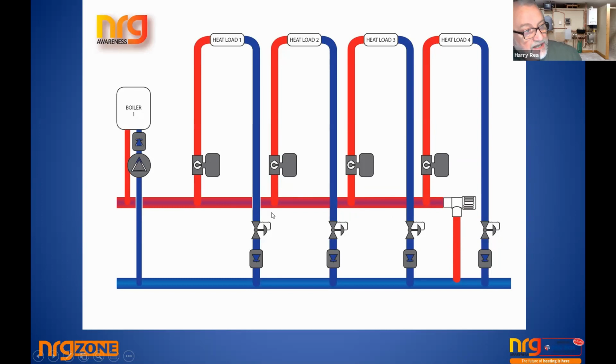But if you see, again, go back to what I was saying in the first place, you might have this set perfectly, and this set perfectly, and then you turn on this, and it's a huge zone, and it's going to take a lot of the volume. And so now you're back compromised again. So the effect of the fourth zone might affect the first and second, and vice versa. The first zone might affect the third and fourth. But that's where the balancing hassle comes in. You just think you have it right, and then you put on one more zone, and it all changes again.